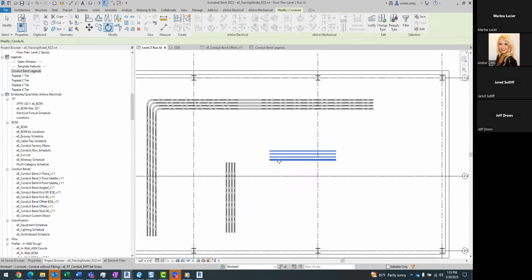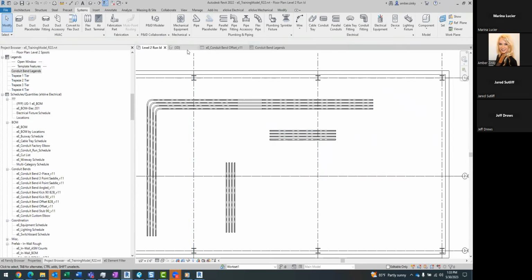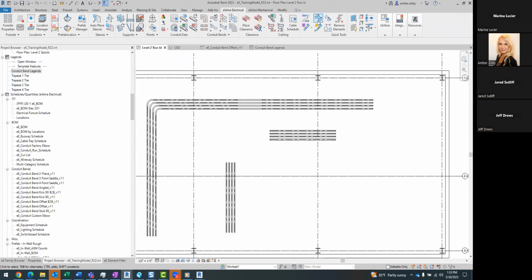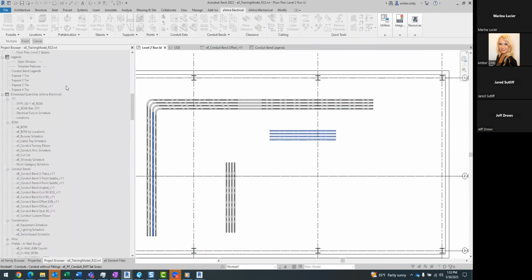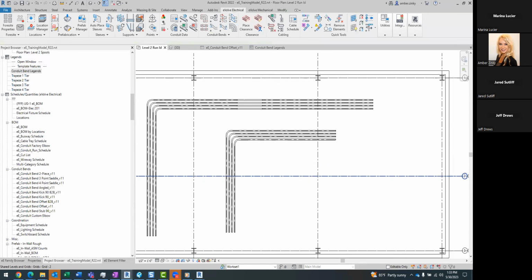It's going to be based on the conduit type and the size itself. So it's going to take into consideration all of that when you are utilizing the Smart Bend multi-trim or just utilizing the trim tool itself. So it's going to take into consideration the size and the type itself to figure it out. It's going to be behind the scenes, more of the development side of how those features themselves work.